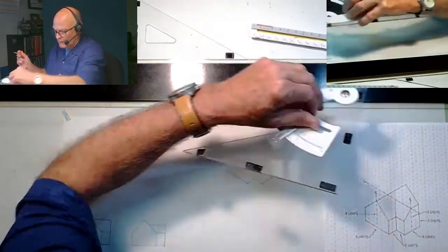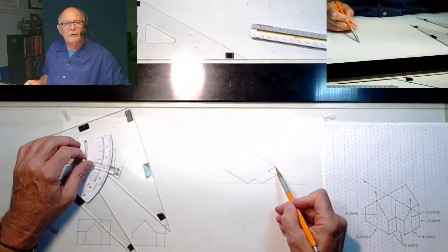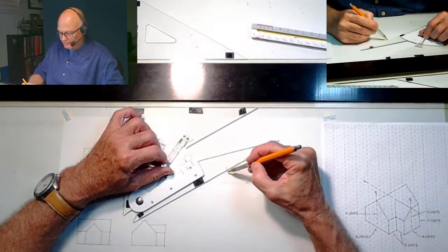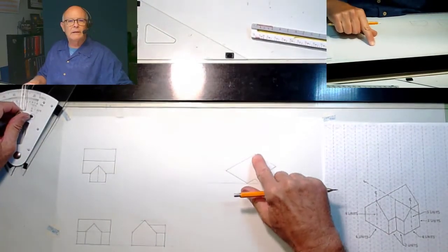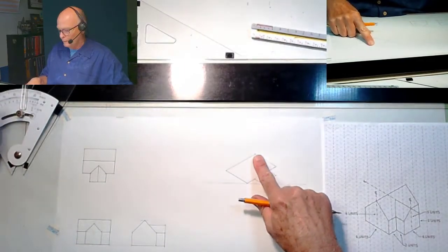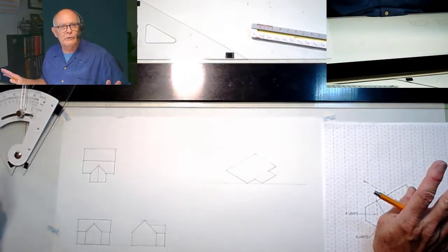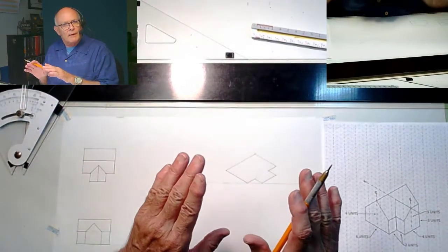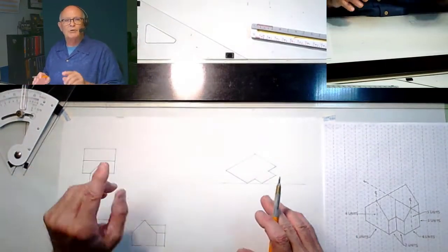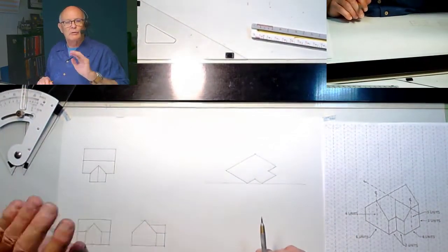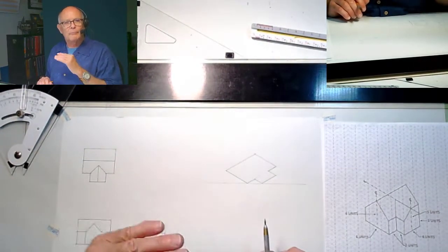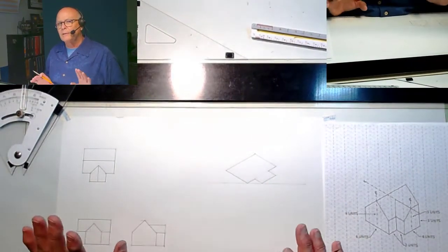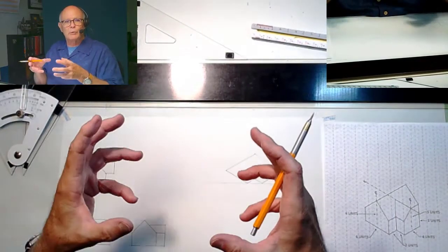And we draw that. Now, remember how we tested this side right here by saying it aligns? Let's check the back side. Oh, look at that. That line connects in with that one, again, on the 30 degree. So 30, 30, oh, these are all 30 degrees off horizontal. So that is the floor boundaries of this object, taken in isometric using a 30-degree base angle off the horizontal. So now that we have the plan, we can now start to project upward to create the form.